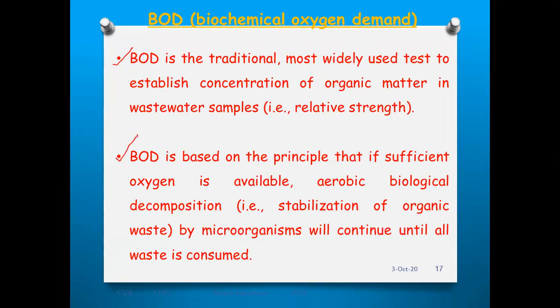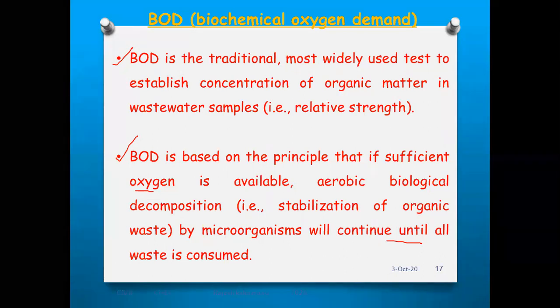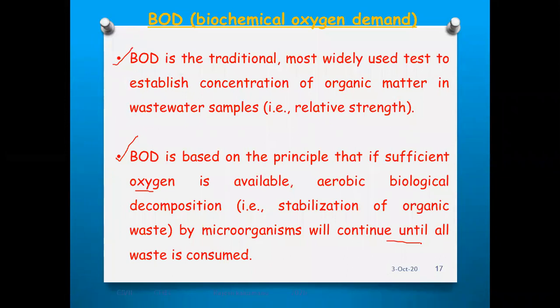BOD is based on the principle that if sufficient oxygen is available, aerobic biological decomposition by microorganisms will continue until all waste is consumed. So what it is saying is that if sufficient oxygen is available in the water, aerobic biological decomposition starts, right? By microorganisms it will continue until all the waste is consumed. So this aerobic biological decomposition takes place in wastewater when the oxygen is available. Okay.